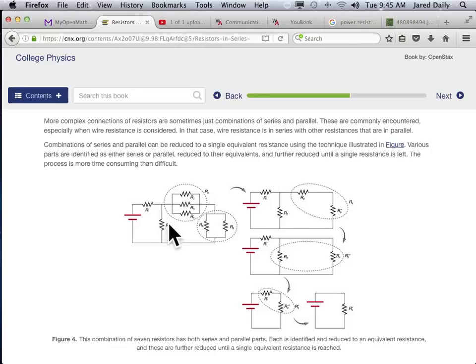So with this circuit right underneath it, calculate the equivalent resistance for these two in parallel, do those calculations, replace them up here, draw a new circuit. Do the calculations for these two in series, draw a new circuit, replace the resistor with the new one in series. Keep doing it until you're all the way down to the simplest circuit you can get.